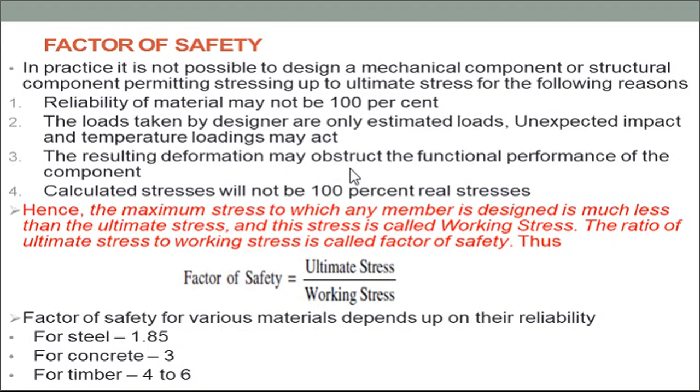The resulting deformation may obstruct the functional performance of the component. This is also one of the reasons. Calculated stress will not be 100% real stress. What is calculated in the office and what actually occurs in practice on the field will not match. Hence the maximum stress to which any member is designed is much less than the ultimate stress. That's why at the time of designing we take a stress below the ultimate stress.